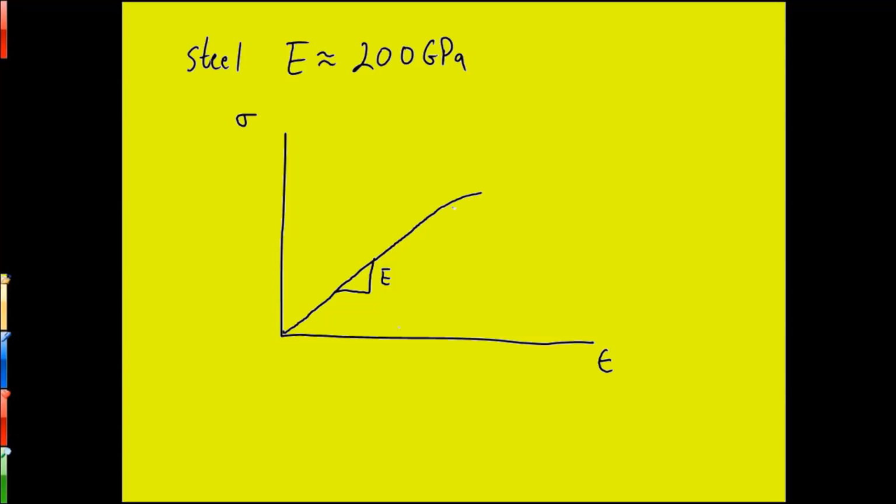And when we release the material, it may not actually go back to 0 anymore. It may now come back down to some small strain that's basically a permanent deformation. And we define the stress where this starts to occur. We call that the yield stress. So if we go above the yield stress, then our material is not going to return back down to where we started. And there's all kinds of patterns that can happen up here, but as we continue to stress the item, eventually we'll get to the point where it just breaks.